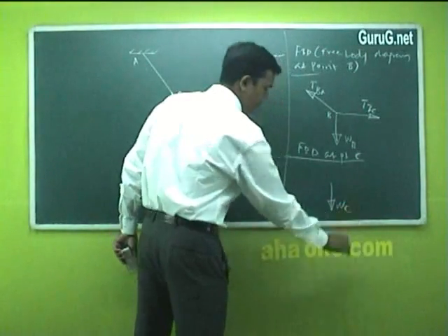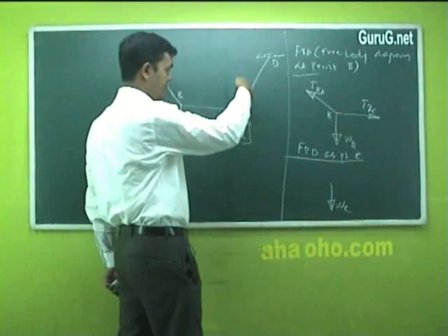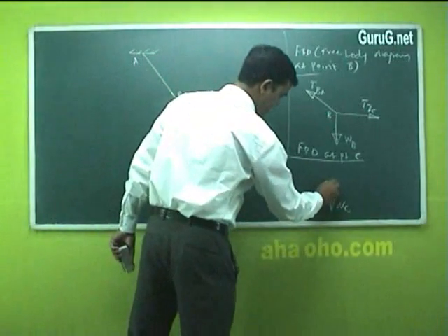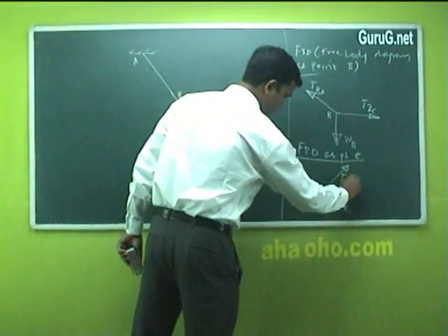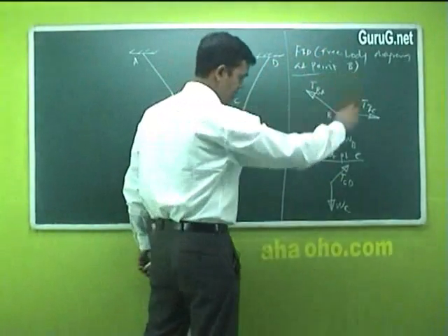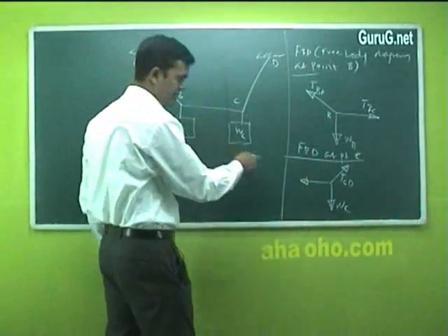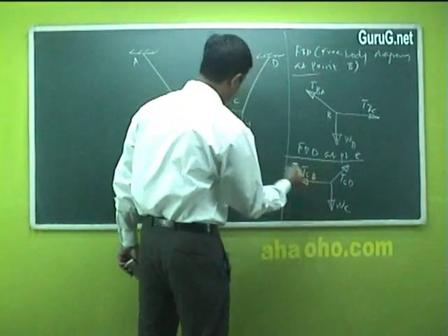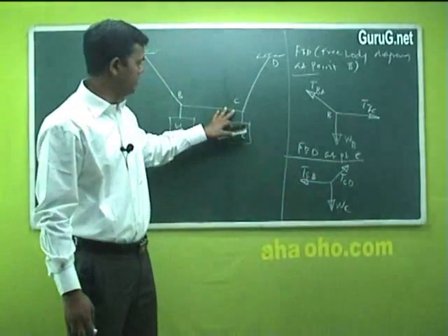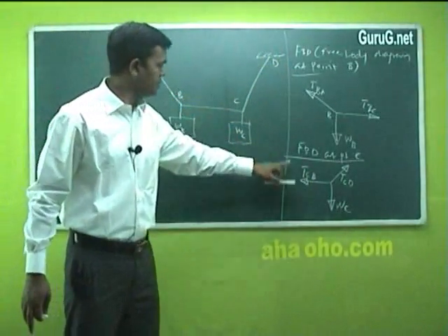Vertical, it's C. Weight at point C. Then, in the inclined direction we have tension from point C which is pulling towards point D. I will just indicate in this arrow mark: tension from point C to point D. From C to D, the first letter indicates from where it is being pulled, C to D. Then again a horizontal line which indicates again from C to B. It's tension from point C to point B. So this becomes, I hope you can understand, the first diagram shows the forces at point B, free body diagram, and this at point C.